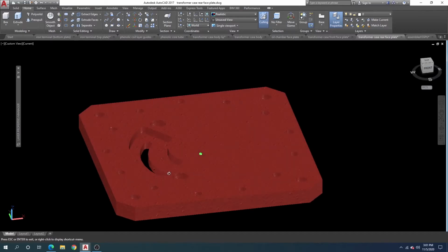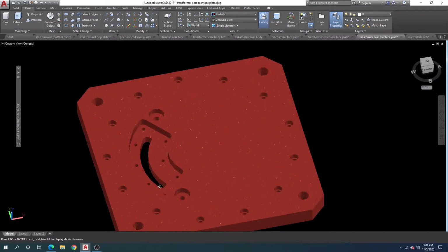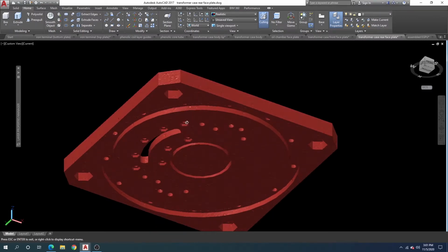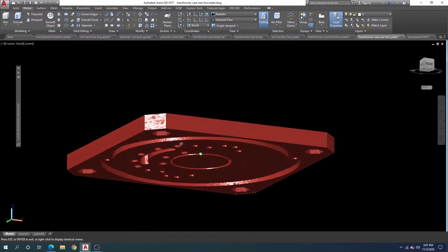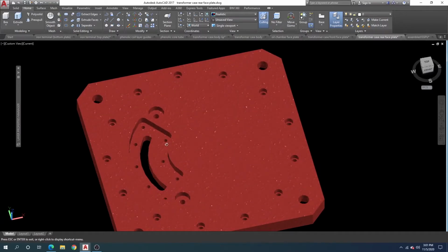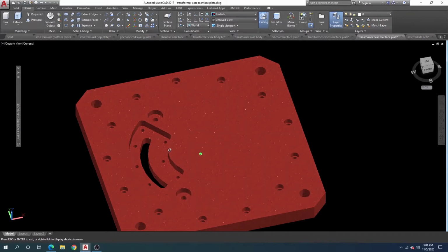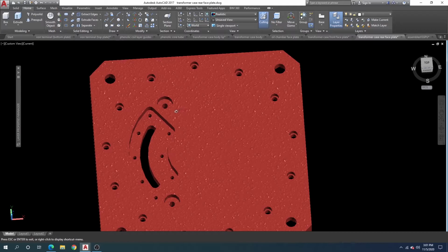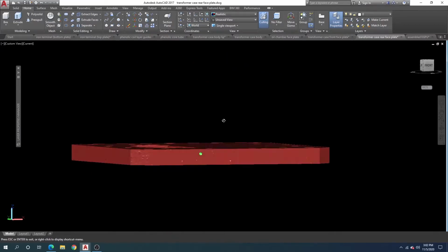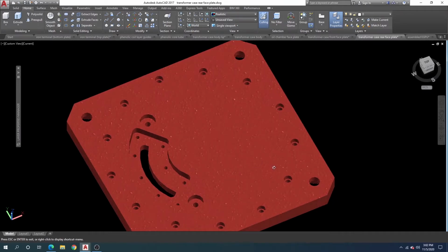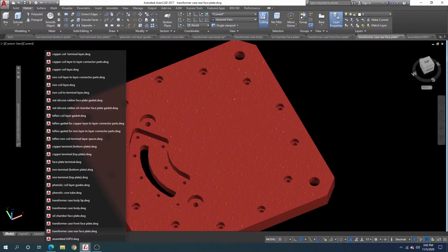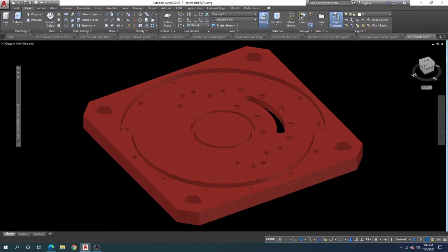Okay, and so when you screw this thing together, you can put a little silicone glue in there, glue the hex nut there, and then when you put this lid on and you bolt it, the bolt will screw into that nut. Okay, these are for the rear terminals, and that's basically it for this thing. So, okay, let's go back to the assembled thing, and that's this right here.